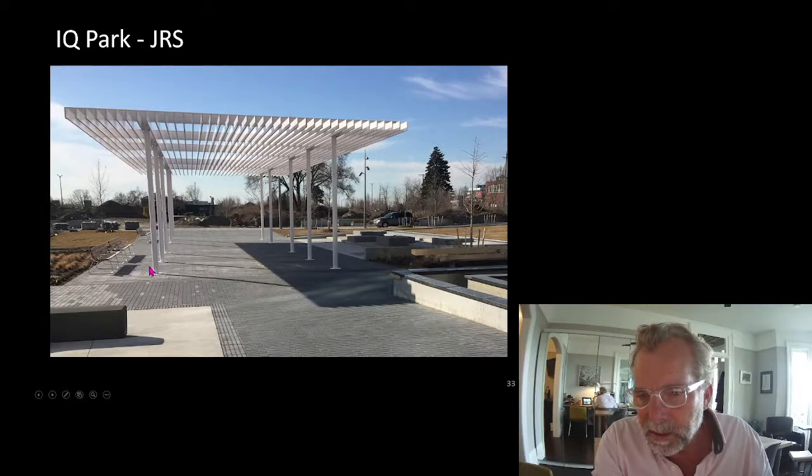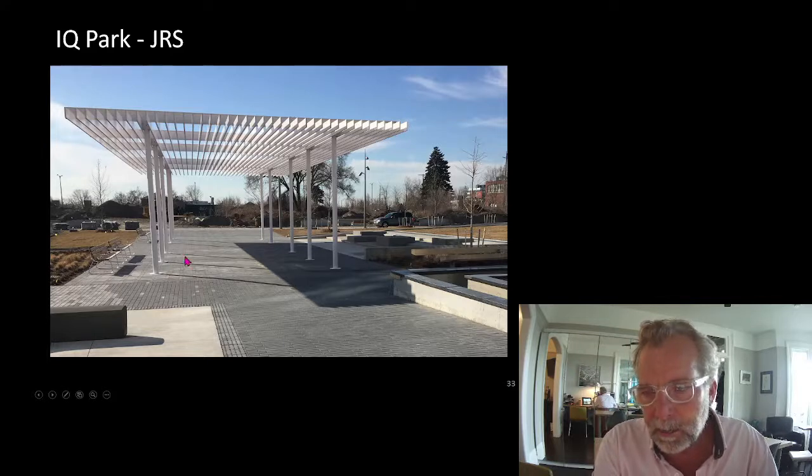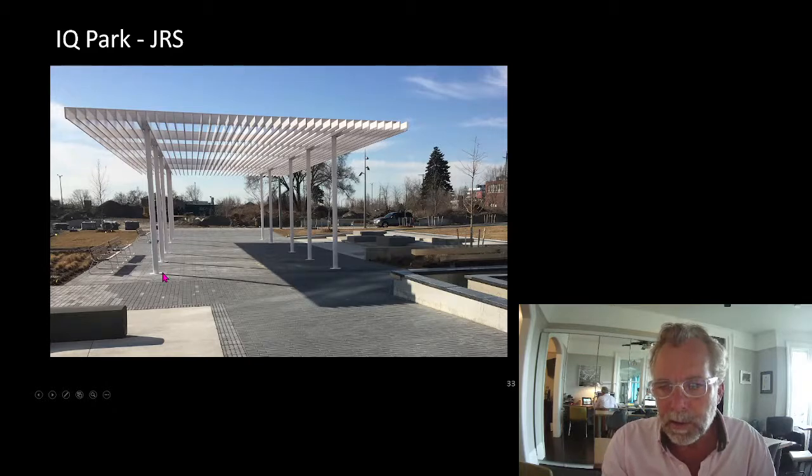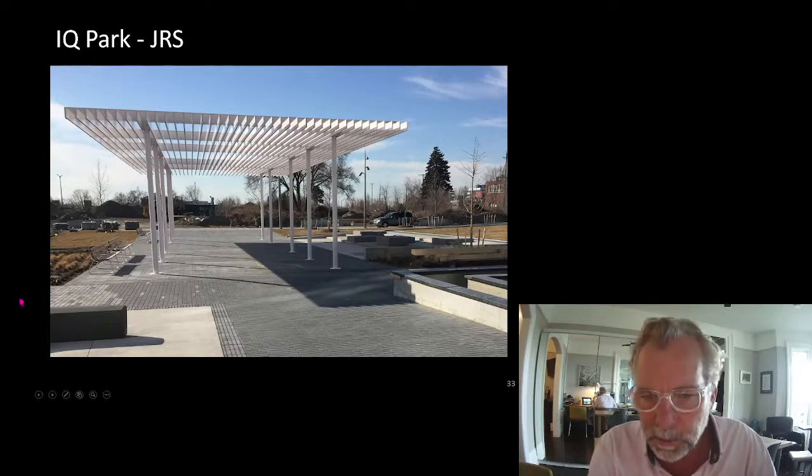I'm going to just point this out. This is a very vulnerable detail, notwithstanding that we do this all the time and architects really like it. The coating on the column down here at the base is vulnerable to salt and to scuffs and due to shovels and everything else you can imagine. What we try to do is lift the base of a column on a little pedestal if it can be tolerated. If it can't be, we feel like we need to advise an owner that they're going to have a maintenance situation.